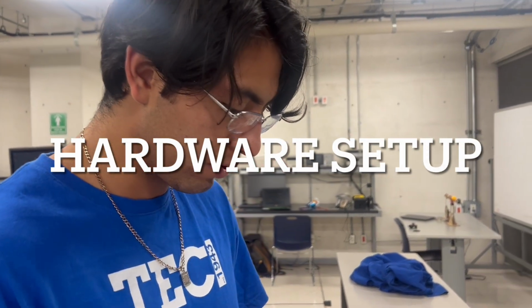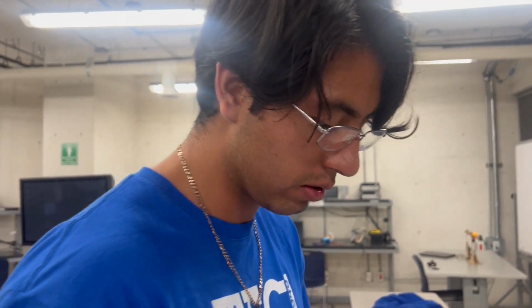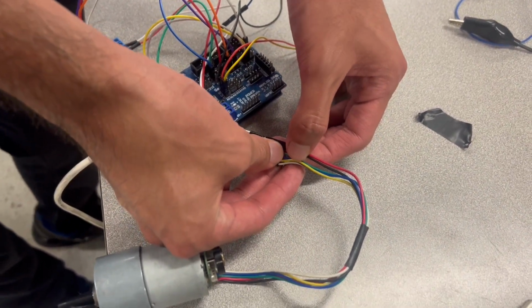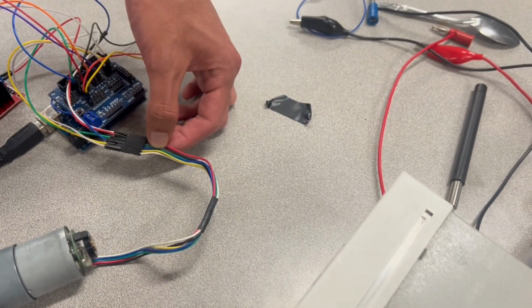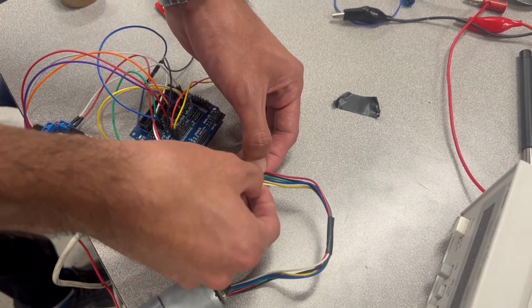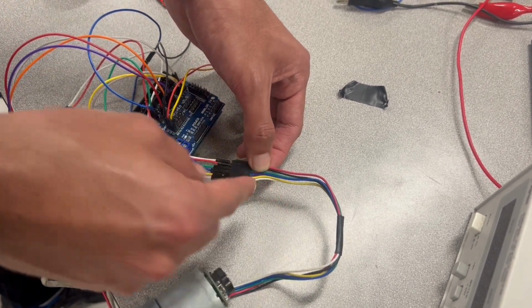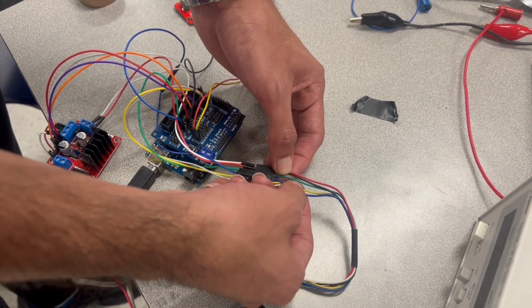Okay, well, so first of all, to connect this circuit that we have, we need to know which connections we had in the motor. In this case, the red cable and the black cable are the ones that we're going to connect to the voltage. Also, the green and the blue cable we are going to need because it's the encoder. This is the voltage, and this is the ground. The green is the ground.